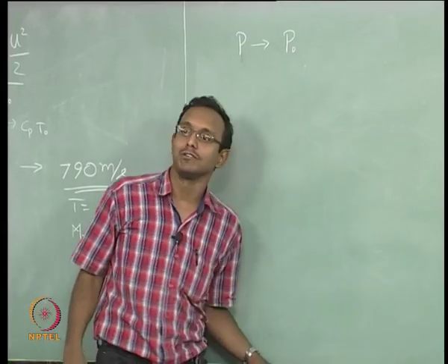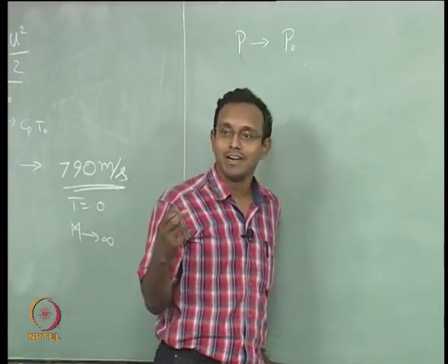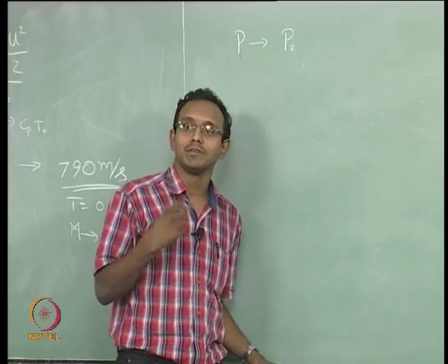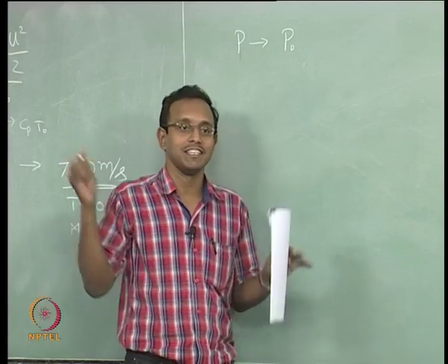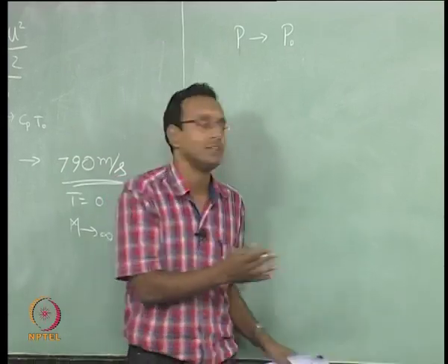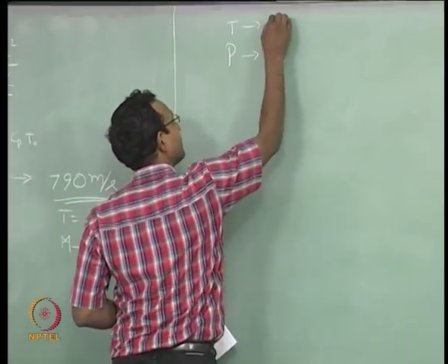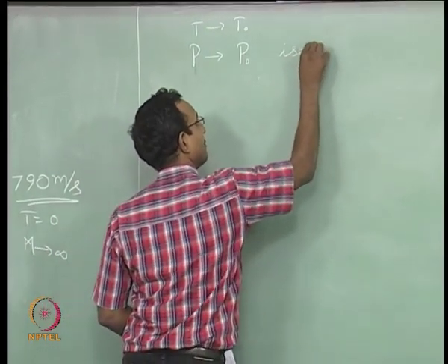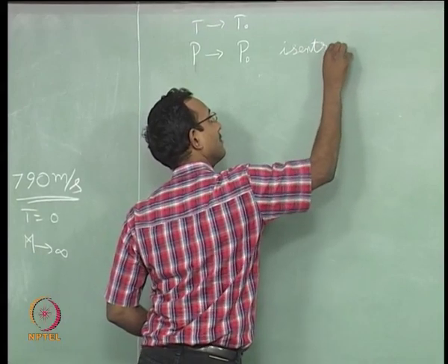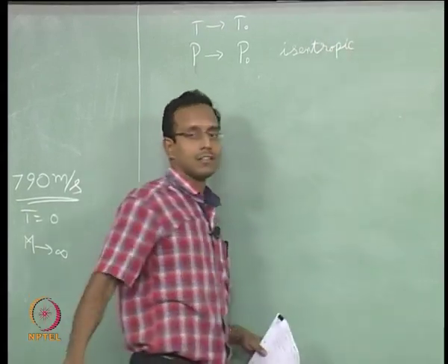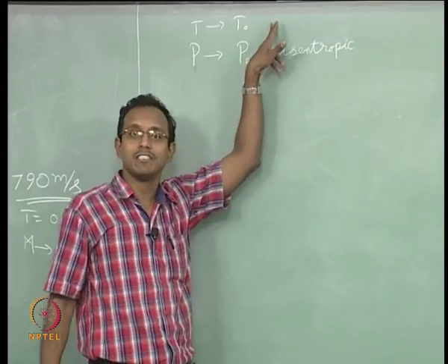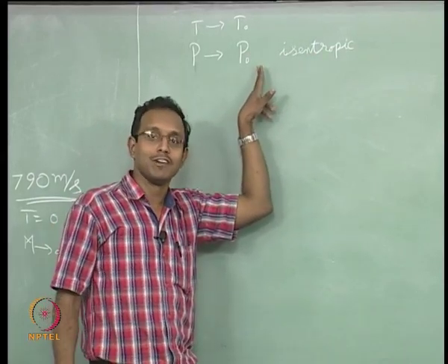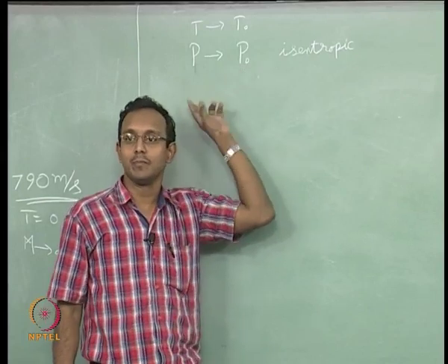Okay. So, we will pick isentropic process, where I am going to think about the pressure of the gas going from P to P0. Already we looked at adiabatically taking the gas from some temperature T to T naught. How did I do that? Decreasing the velocity slowly to 0 velocity. So, I already did this. Now I am going to say this one is done isentropically. That is, previous one adiabatic was enough, now I have to say it is adiabatic reversible.